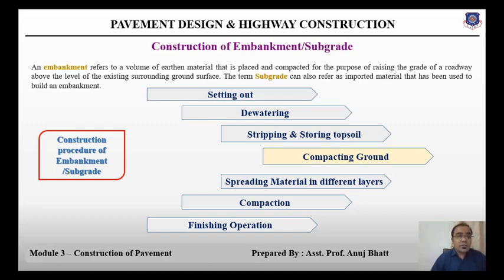If the degree of compaction is higher, then that is not considered a proper compaction. The excavation at approved borrow areas shall be carried out with the excavator, and transportation of excavated material shall be done by dumpers, tractor trolleys, etc. The natural ground soil shall be tested for its suitability.